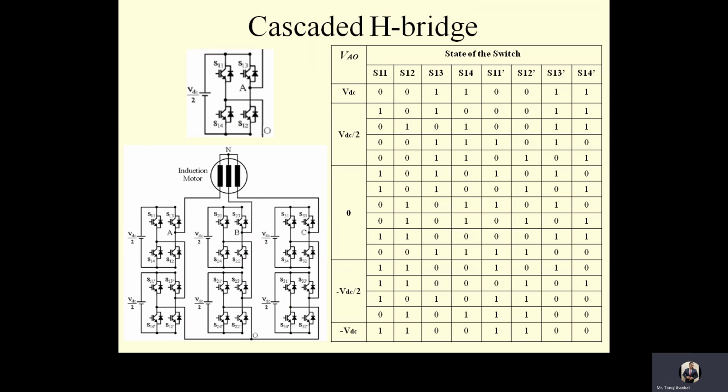Each inverter cell has an identical structure, and thus the extension to higher levels does not add more power bus complexity. Also, components like capacitor voltage balancing or clamping diodes or capacitors are not required.